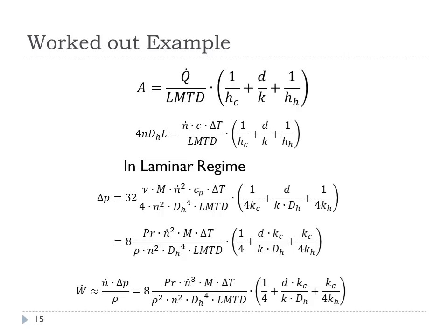And then if you assume some type of isothermal compressor, you can make an approximation to how much work is consumed to overcome that pressure drop. And you now have an equation that shows how the work is going to increase with the flow rate cubed, right?